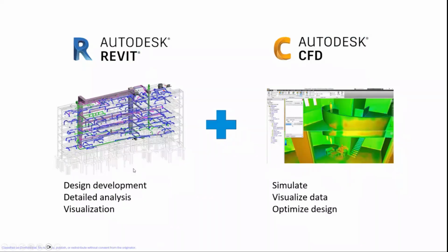For Revit, normally Revit has the functionalities for design development, detail analysis, and visualization, but we can't know exactly how the fluid is flowing in the HVAC system or in the building. We cooperate with CFD by importing the Revit model, but the one that we need must be a simplified model. Taking the full detail building in Revit and dumping that data to CFD directly is not possible